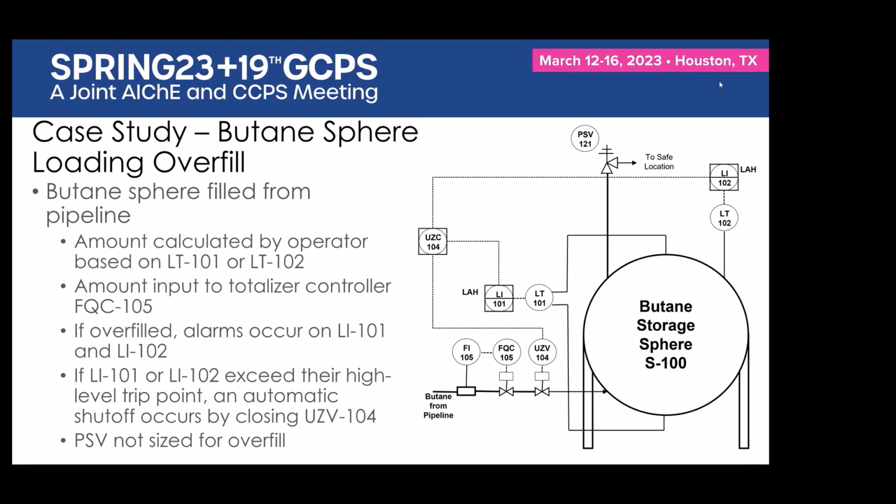So when your real situation doesn't match those simplifications, you have to use your engineering judgment to most accurately model reality. And in terms of restrictions, either from the 61511 standard or the OSHA PSM rule, I don't see any restrictions on the extended fault tree analysis.